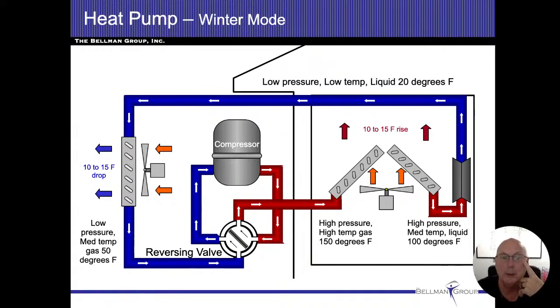And we don't want to put heat pumps on setback thermostats where we change the temperature a lot, like a Nest where we'll lower the temperature or let it heat up in the house when we're at work, and then all of a sudden about a half hour before we come home, we turn it on and expect everything to drop. It doesn't work well that way. Heat pumps, when they're working for heat, we want it to stay consistent. All right, we want them to be on and maintain a steady temperature. That's when they work best.